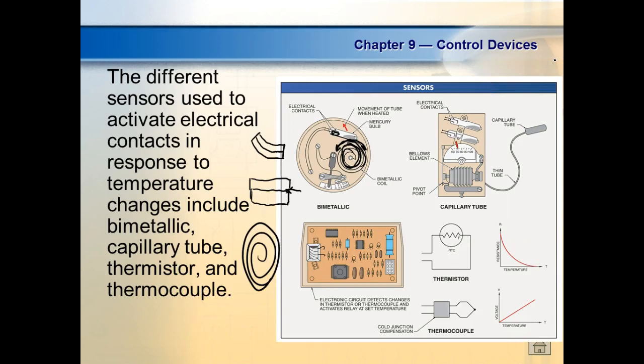Another thing we have is we'll use a bellows tube. They had one of these sensors out there on a hot glue gun. They packaged the milk in a package, sealed it up, and then put it in a box. And then of course they glue the box together, right? The actual gluer, they wanted to keep it at a certain temperature. So instead of putting a temperature sensor in there, they put a capillary tube in there. And the capillary tube ran up to the bellows. And what happens to air when it heats up?